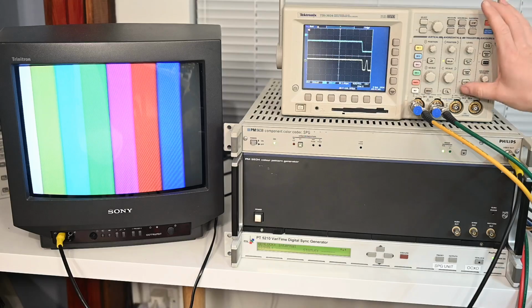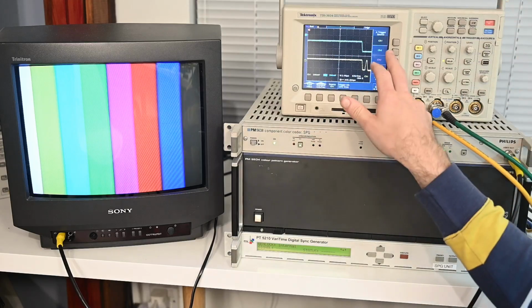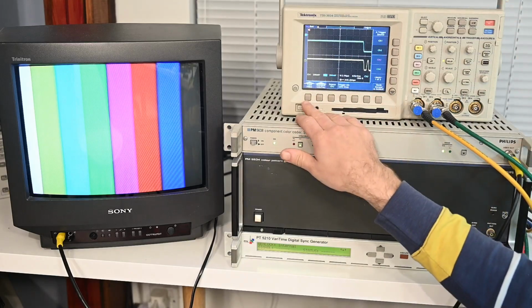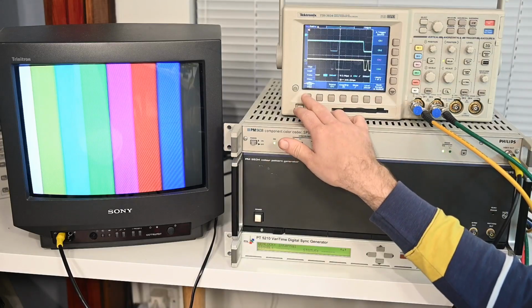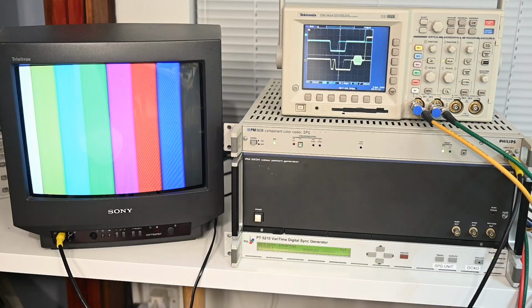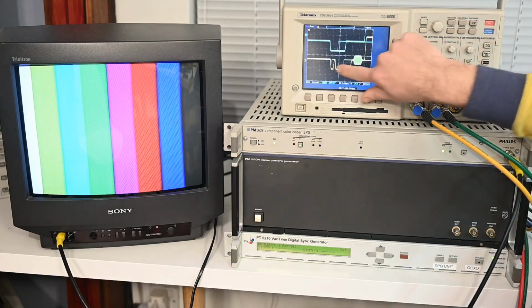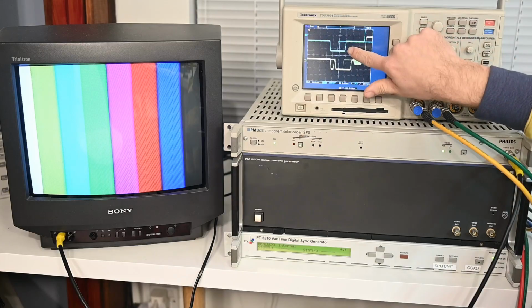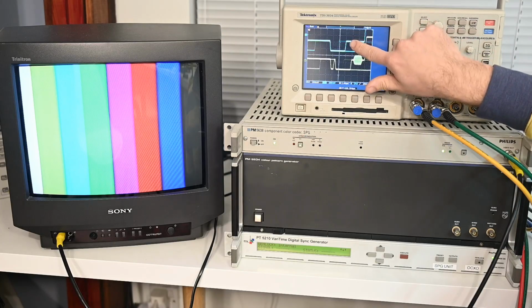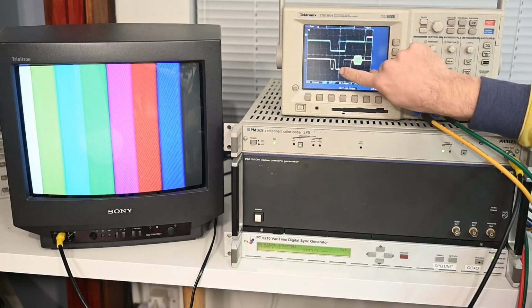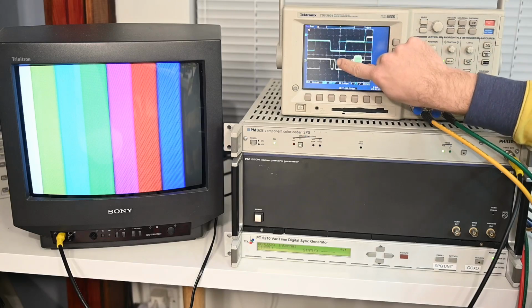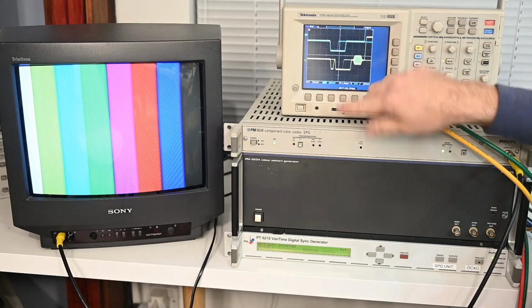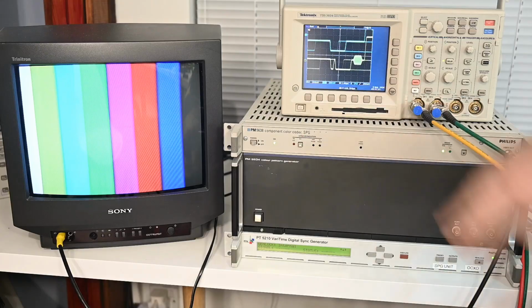Well, if we move the trigger to channel 2, which is the green output from the Kona, move that to an edge. Well, we can see we've got a bit of a problem here. So the yellow trace is the composite output from the PM5638. The blue trace is the green output from the Kona. Now notice that we have this nasty spike in the middle of the sync pulse from the color coder. And you might be tempted to think there's something wrong with it, but there isn't.